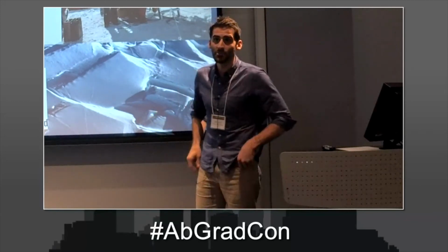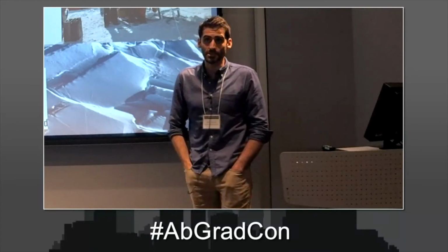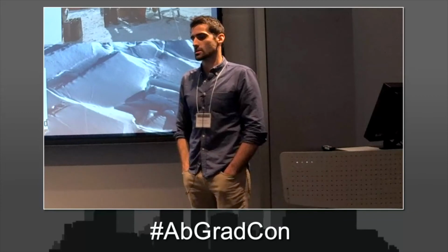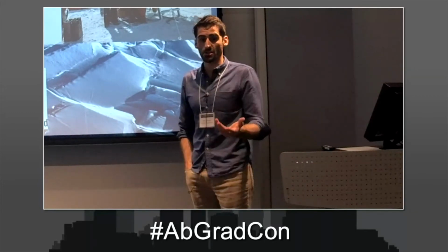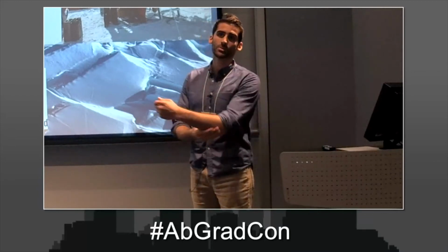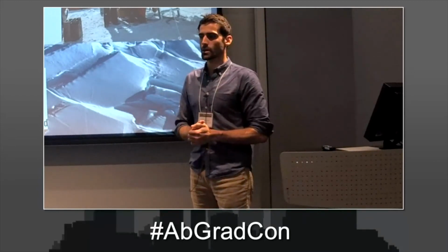People are working on that, but it's not clear exactly what the best way to solve it is right now. On Earth, it's a little bit easier, and we can do things with both optical and acoustic modems. So optical data in water, if the water is very clear, you can do it with pulse lasers and get actually pretty good data rates, but you're limited to just a couple hundred meters, so not really good for the scales that we're looking at here.